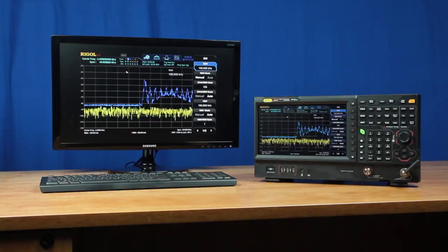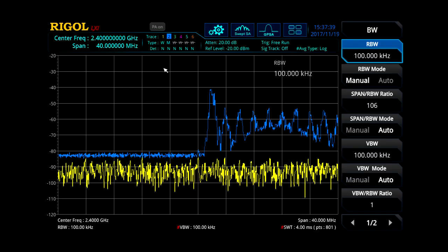Because the detector sweeps across the span, the instrument can't capture all the frequency components at once. Typical sweeping analyzer sweep times are measured in milliseconds to seconds. The RSA5000 works as a sweeping analyzer for important high-accuracy characterization, but even in a fast sweep, it can't quickly show activity in the Wi-Fi or Bluetooth bands.